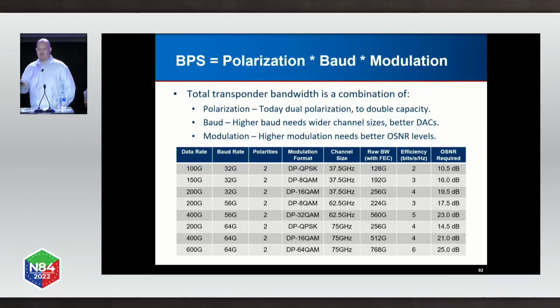There's tons and tons of it that'll be out in the wild for a very long time. And it will run down to an OSNR of 10, and this is old, by the way. Modern DSPs probably just knock a few dB off of all these numbers. That'll run across the planet and still come out just fine.